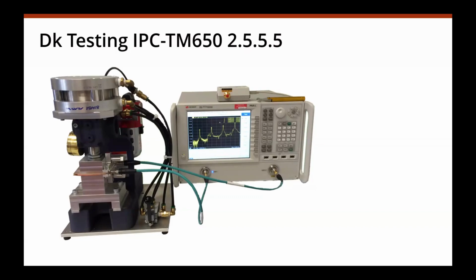What I mean with good indication is the Dk we are testing here is not measured to get an absolute value. You are doing that testing to make sure that batch over batch over batch, over time, your material is the same. So you are not so much concerned about the absolute value, but you are concerned about changes over time. And that's something you can perfectly test with that method. So that's the reason why the industry is using methods like that.